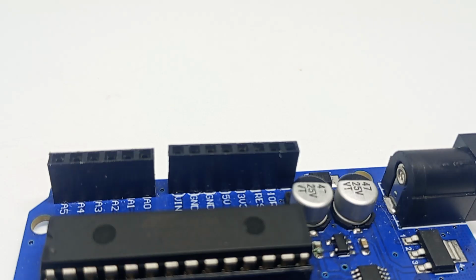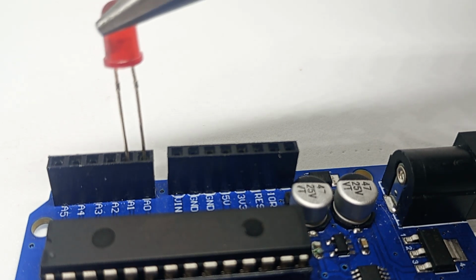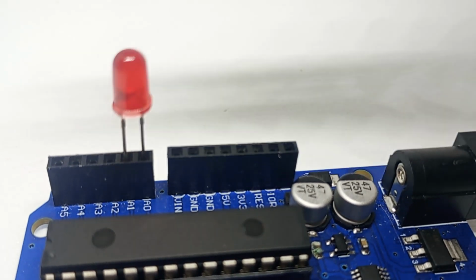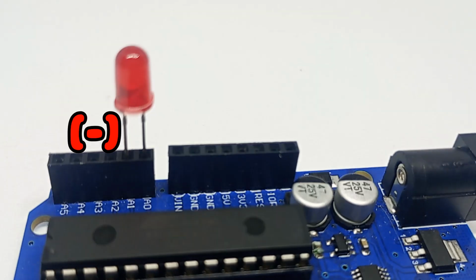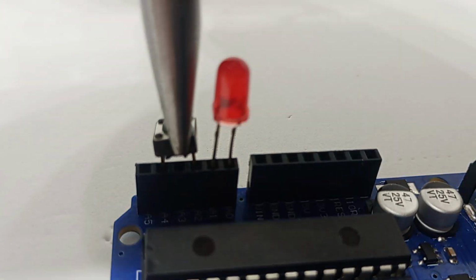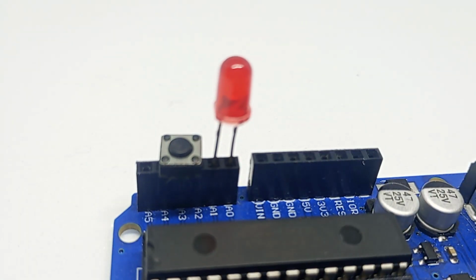for example, let's try the above mentioned. Let's place an LED diode between the analog 0 pin and the analog 1 pin, with the anode or positive pin in A0, and the cathode or negative pin in A1, and place a normally open button between the pins A2 and A4, directly connected to these pins.